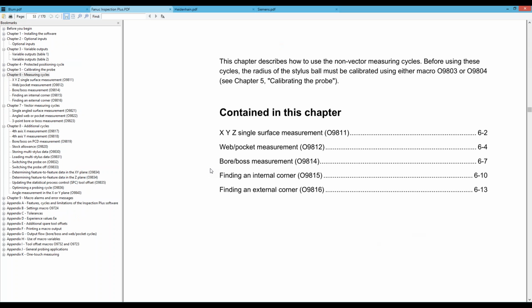But before that, let's talk about how the probe is working, how SolidCAM is connecting to so many different devices and different cycles and different controllers on the market. If we are looking at the packages of measuring cycles, and I'm looking here at Inspection Plus for FANUC, we see that generally they do the same action.